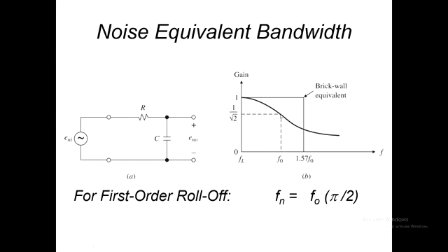If you're using other than sine waves in a system, suppose it becomes a triangular wave when things reach their slew rate, as we saw in the lab, then this index somewhat goes to pot. It's no longer valid. It's valid for sine waves, but not for other waves necessarily.